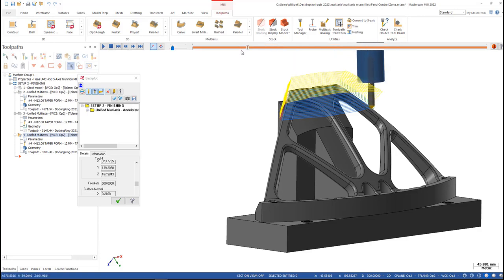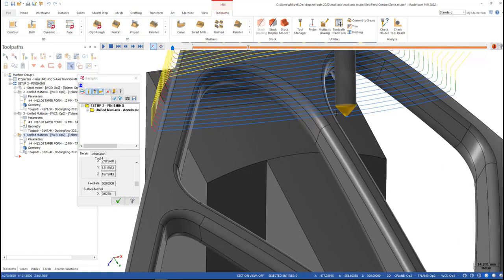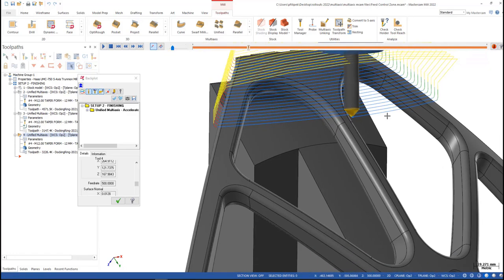So once we come into here, and there. Look at my feed rate in this bar right here. I'm at 2,500 for a feed rate, and I'm over that window. As I get closer to my cut edge, oh, there I am at 500 again for my feed rate, or 100% of what I had set. And that's taking into account that 5 millimeter zone. It comes across at 500, gets past the 5 millimeters, and now I'm going 2,500 again.